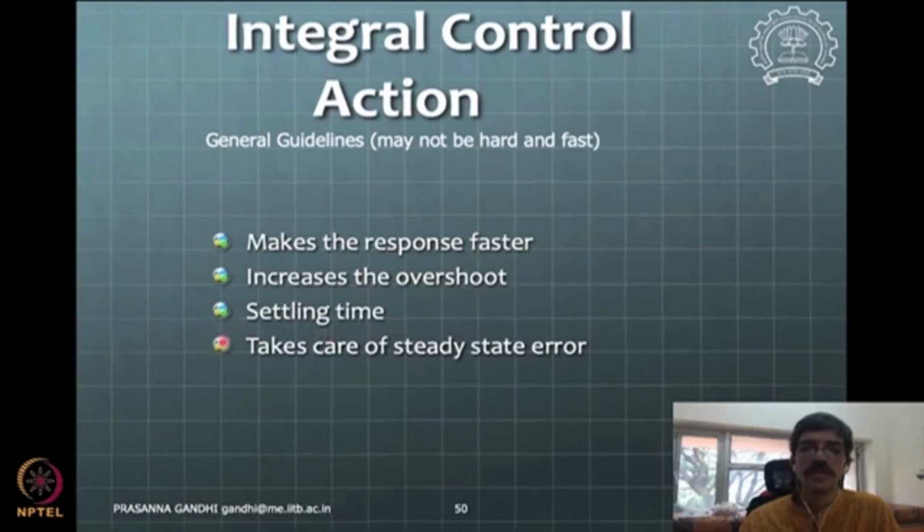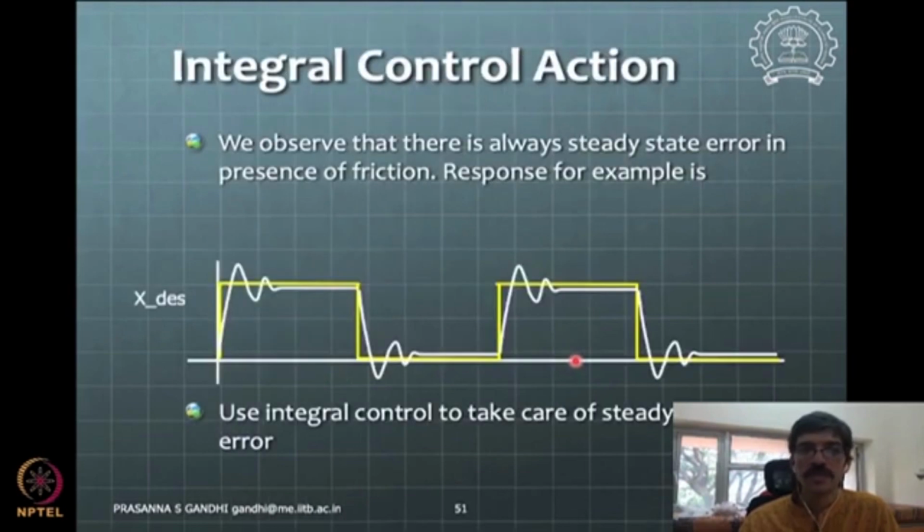Imagine you have a steady state error like this here, and integral control action is there. Derivative control action is stopped because theta dot is 0. Proportional control action keeps going since theta is constant, but it is not changing. Kp times this error will be a fixed amount of input going into the system, but that input is doing nothing, because say for friction, even if you apply a force, the system is not moving. That kind of case will happen here.